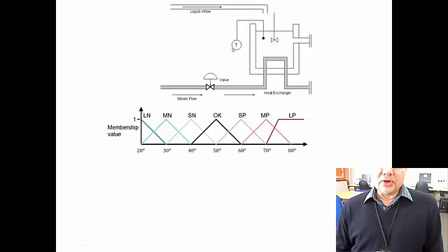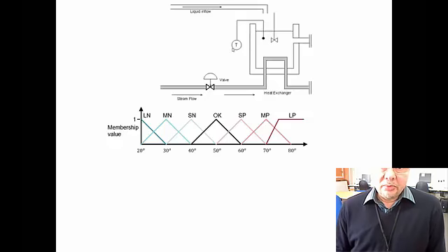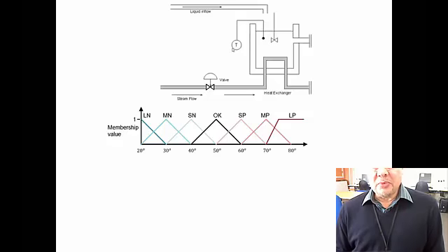We tried first to implement the expert system using crisp membership functions, and one drawback of such a scheme was that similar temperatures, I think the case we considered was 24.9 and 25.1, very similar temperatures, probably the human operator would take very similar action, or actually not be able to distinguish between the two. But our controller using crisp membership functions gave us two different actions.